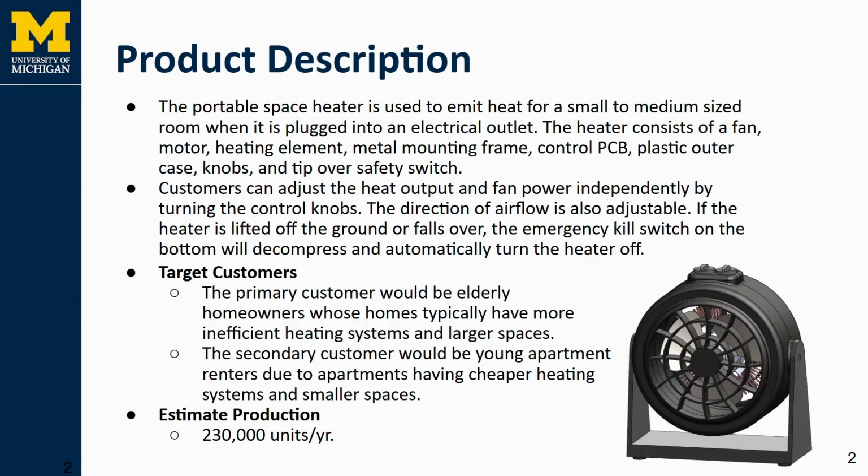The heater consists of a fan, motor, heating element, mounting frame, control PCB, plastic outer case, knobs, and tip-over safety switch. Customers can adjust the heat output, fan power, and the direction of airflow. If the heater is lifted off the ground or falls over, the emergency switch will automatically turn the heater off.